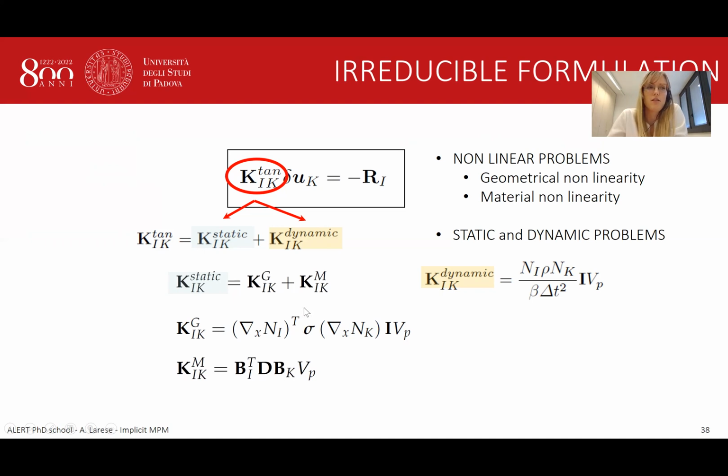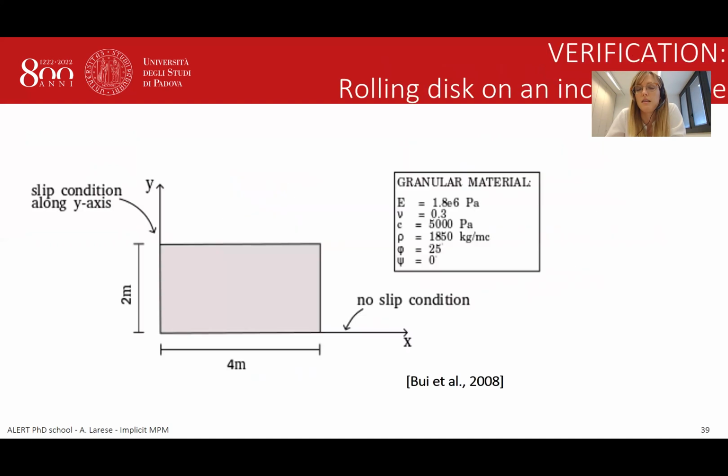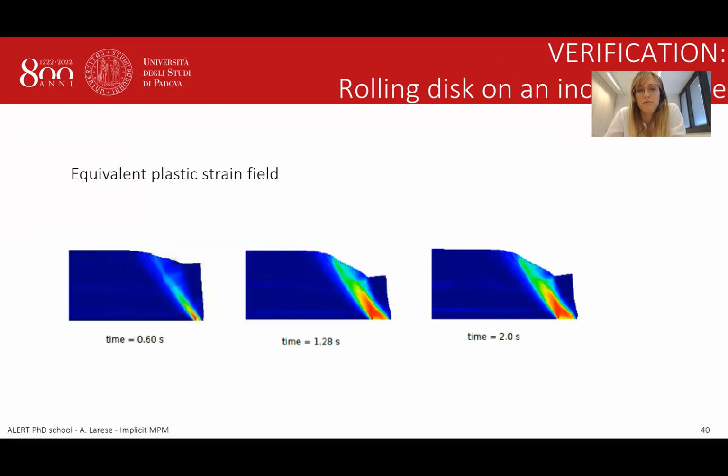So the shape functions are exactly the finite element shape functions, with the only difference that you're not evaluating them at the Gauss points. So you don't know a priori where to evaluate your shape functions, but you have to evaluate at each time step on the position of the material points that you found. But the rest is exactly the same as finite elements. And this is fine. This formulation is absolutely very common in finite elements, MPM and whatever.